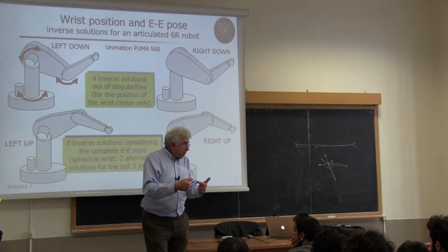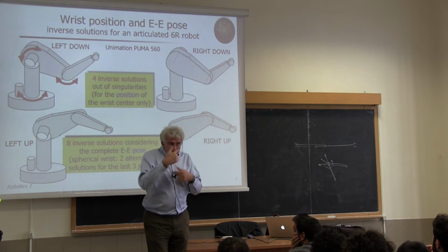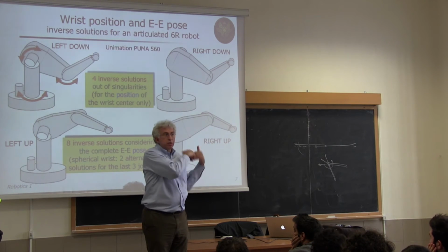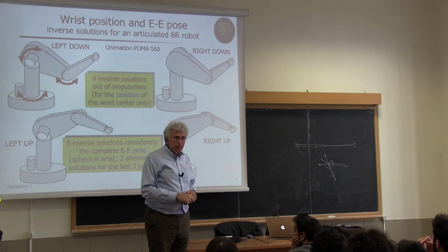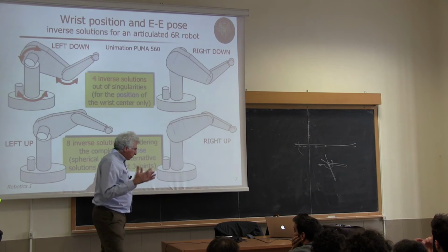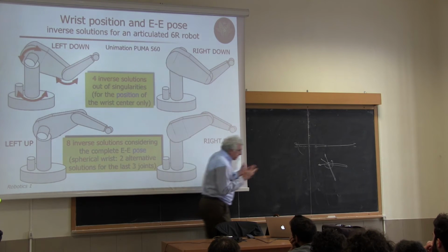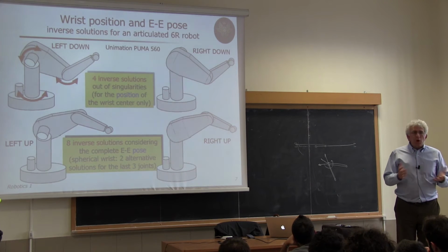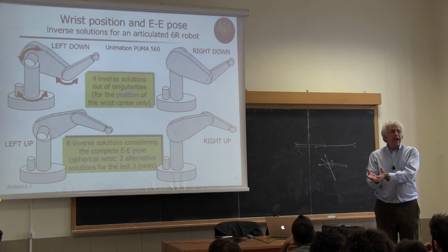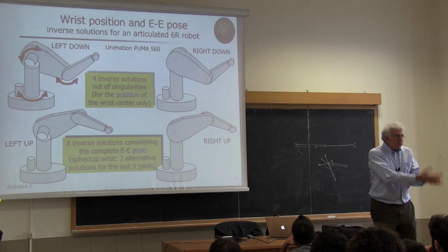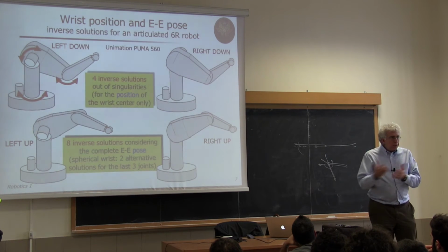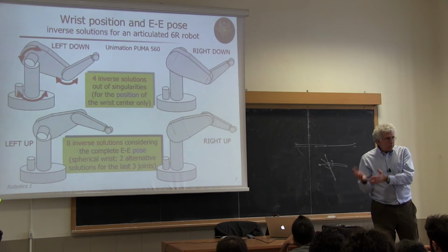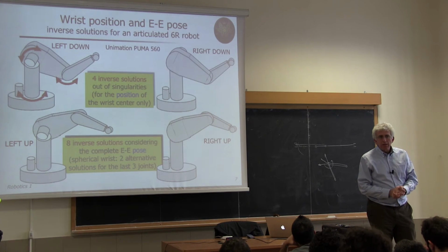And finally, q6 or theta 6 is the third angle around the current z-axis, which is the result of the rotation of the previous one. So in fact, q4, q5, and q6 characterize a sequence of Euler angles. So what? Now we know that if we give values to these, we have an orientation, R. Now the problem is: give me an orientation R for the end effector of the robot, realize it with these 3 angles of the spherical wrist.